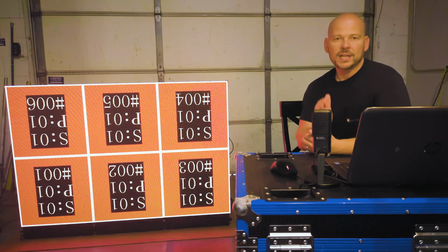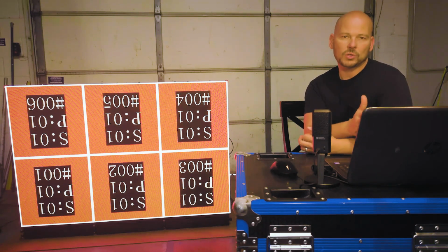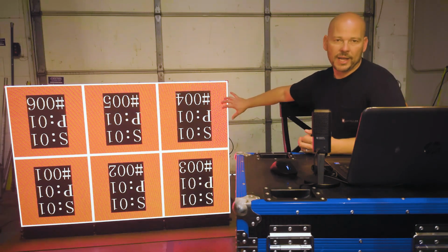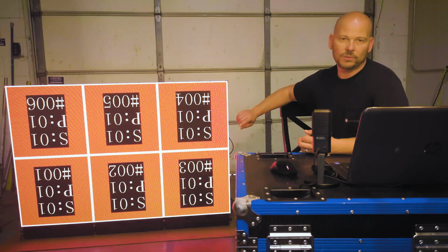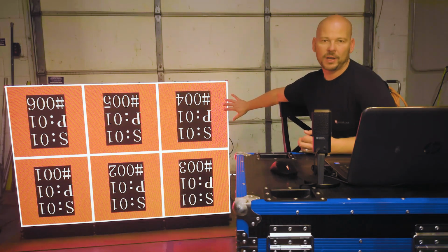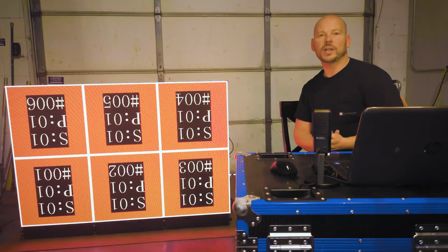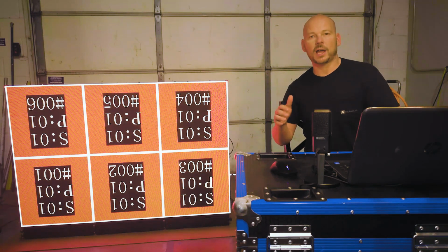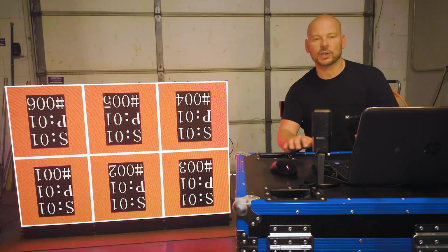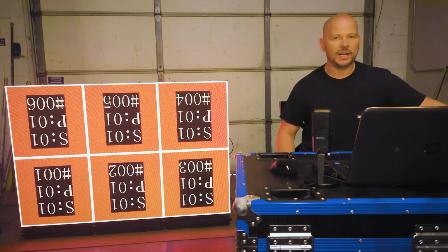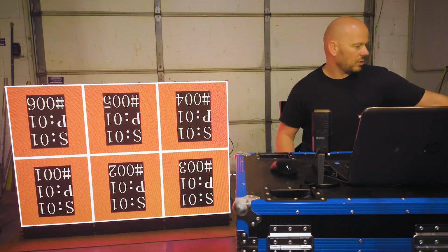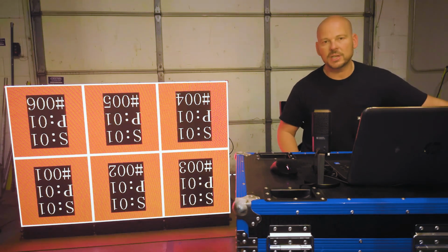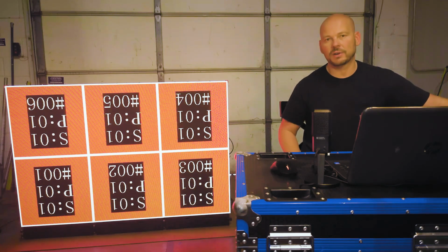What's important about that is by sending it from my software to the wall, and then the wall generating the red, I know that I do have a communication signal, and I know that my panels are responding to my software. If I wanted to send the red or whatever test pattern it is, and I don't want it to come from the panel, but I want it to come from my controller, I would send that data directly from my controller. Most of the controllers we work with have an LCD screen on the front. You just click through the menus, go to your test patterns, and send red from there.